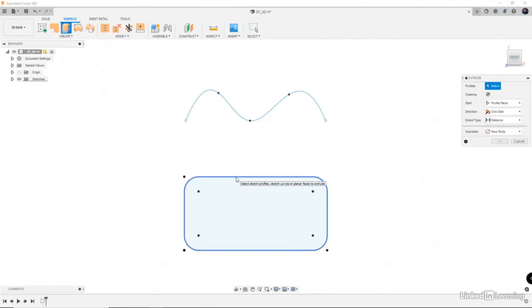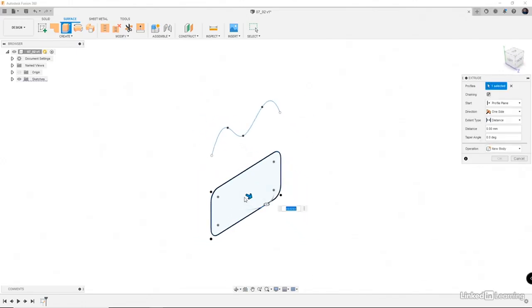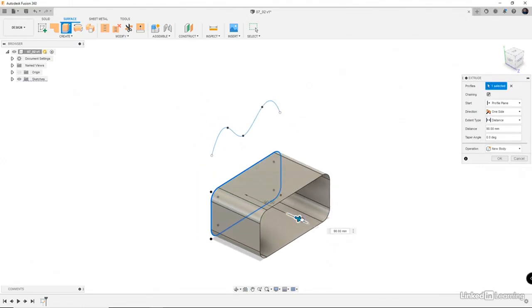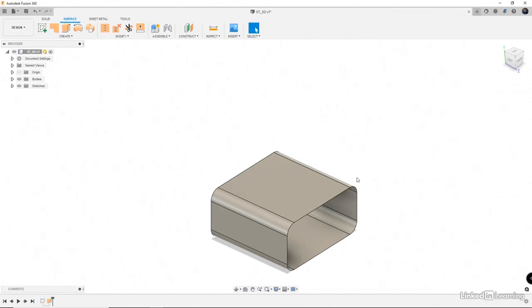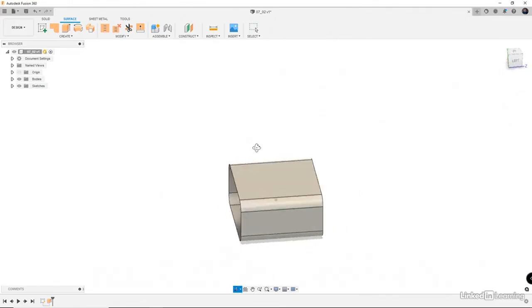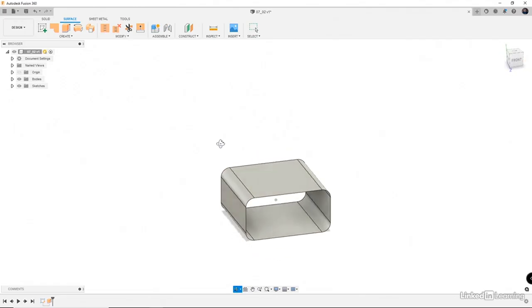So if we select this line, and then we can extrude this, and we end up with this surface only, which is super cool because we can use this as a cutting tool. We could use this to create some sort of other surface and then eventually turn into a solid body, or maybe this is just some sort of reference that we need for machining something or building some sort of other geometry. So let's turn that sketch back on because it automatically turned off.